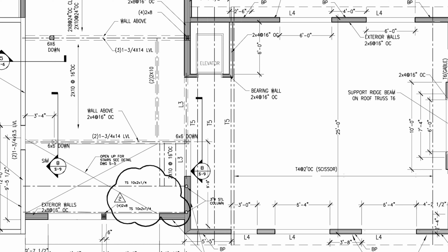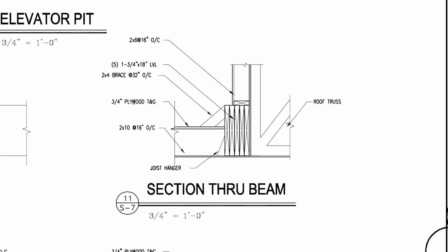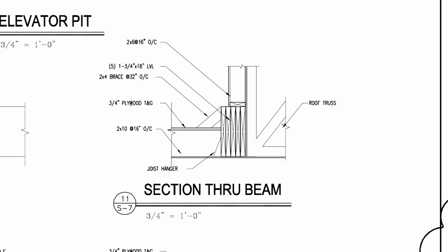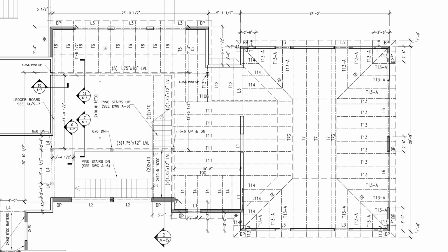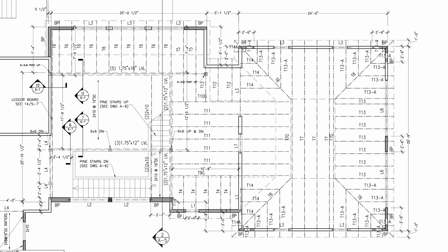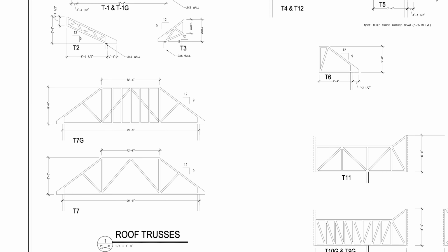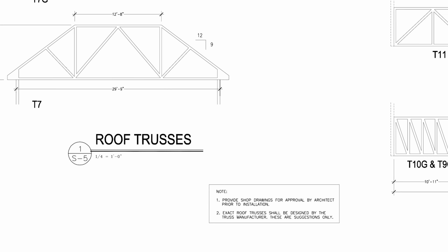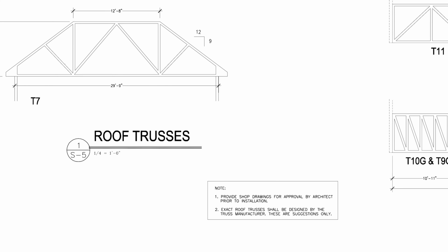And then this starts getting very specific. For instance, this is showing LVLs. So as a homeowner, you're probably not going to be very familiar with those components, but the general contractor will understand all that. Since this is the roof framing plan, they're going to give this drawing to a manufacturer of trusses, and they're going to provide their own shop drawings that they create, which you'll have to submit to the building department, or an inspector in the field. They design based on the architectural structural drawings, but the sizes, the pitches.